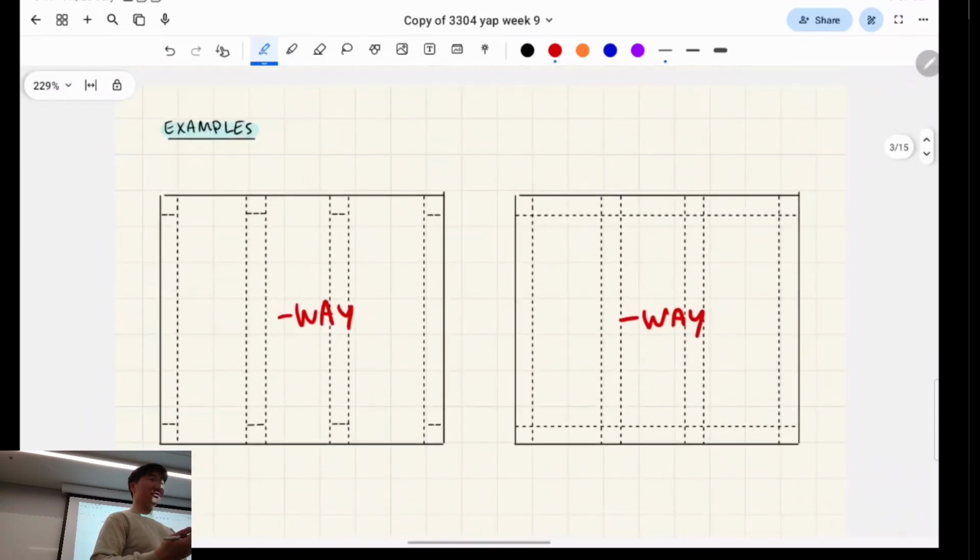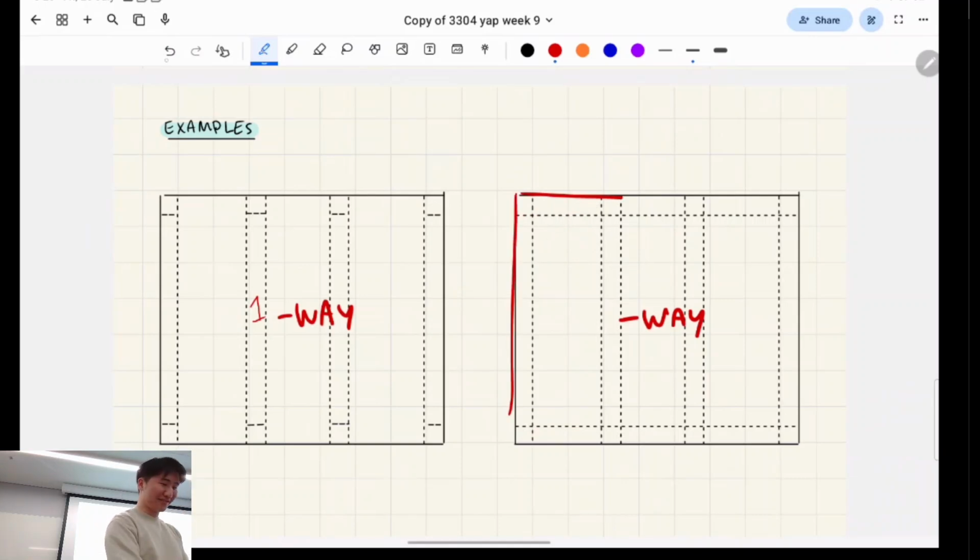You tell me if they're one- or two-way slabs. So this first one. Very good. This second one. You sure? So the beams are there, but think about the aspect ratio. Basically this aspect ratio is like 2 blocks and this is like 6 blocks. Let's think about it like Minecraft blocks. It's going to end up transferring like this, because the path of least resistance is in that one direction. Okay, so this is a one-way slab.